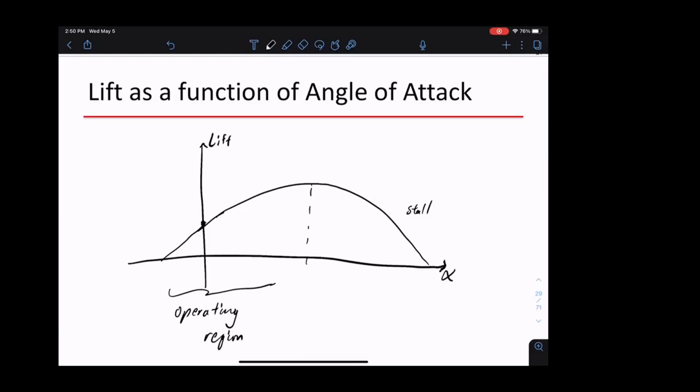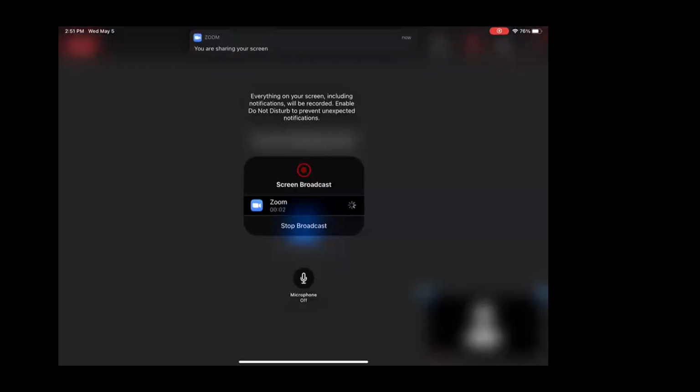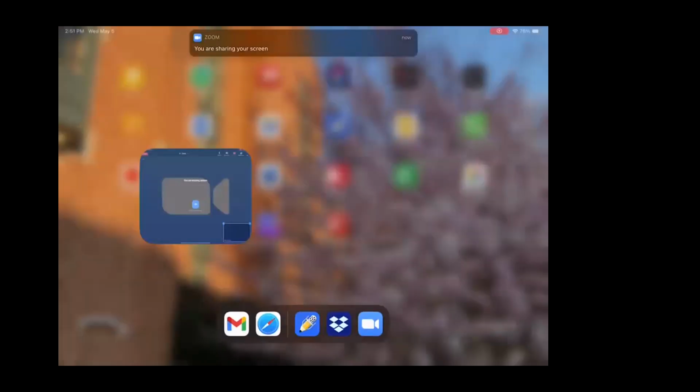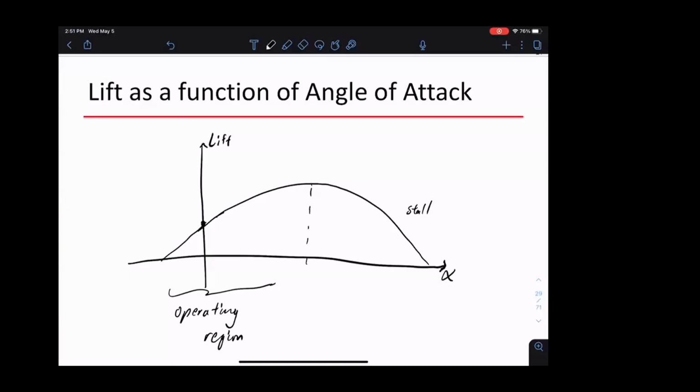So for wind turbines, a lot of design is about how to generate power, but an equal amount of design is how do I get rid of unnecessary power? Nowadays it doesn't happen as commonly that a wind turbine just blows up and flies apart, but it does still happen. So this is where you want to change your angle of attack. You don't want too much lift, more lift than you can handle.